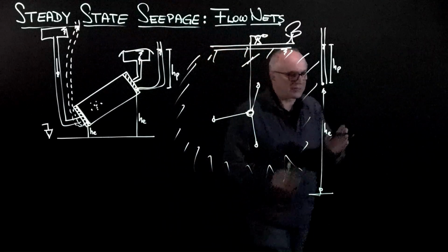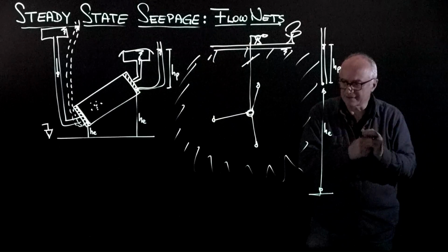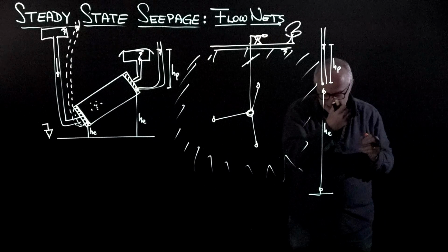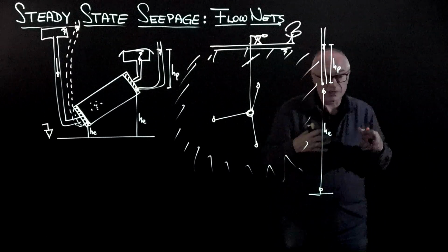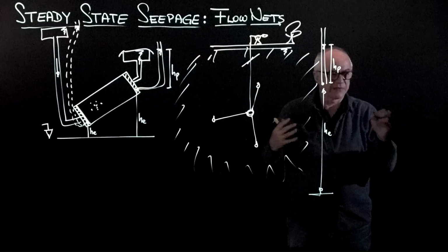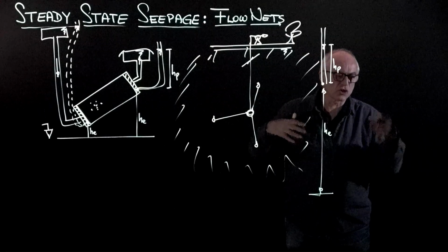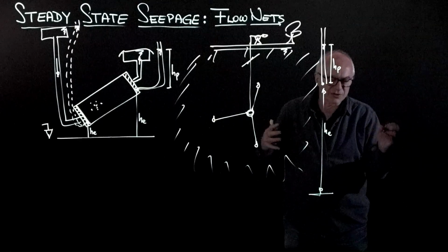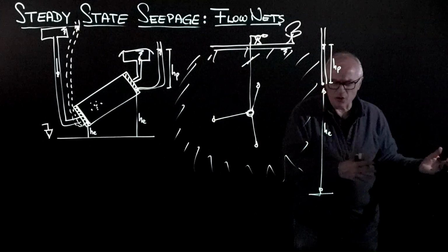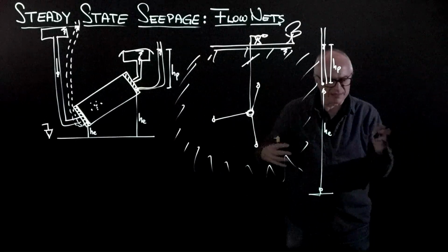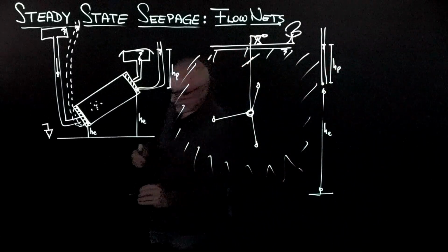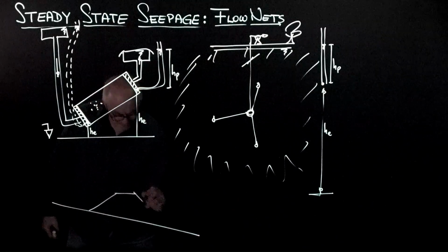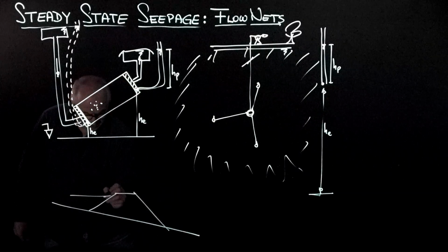The last example that we're going to place in this small region of the board is another fairly common case in geotechnical engineering, where we have the phreatic surface, and the phreatic surface is not constrained. It can migrate up or down with the flow, and so that is a typical case of slopes, or the simpler situation would be to think of an earth dam. So let's assume that we mount an earth dam here, and this is a reservoir.